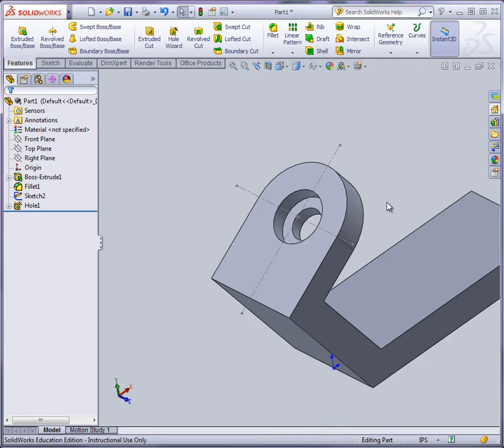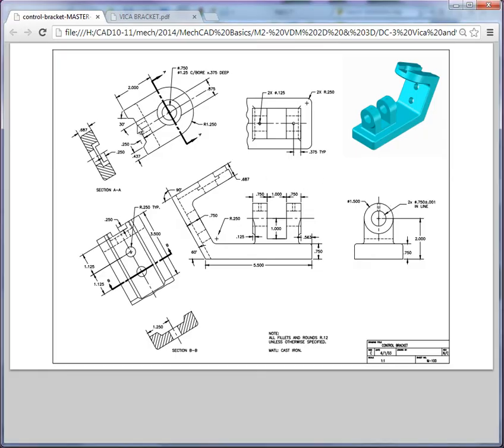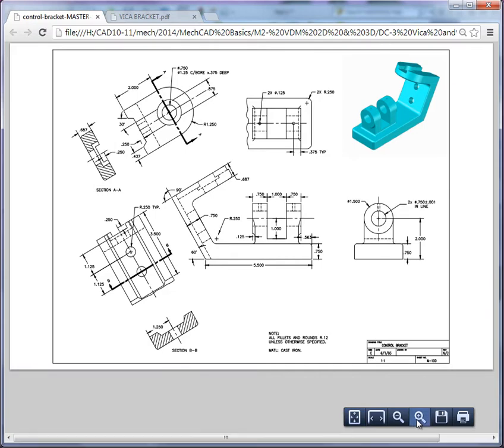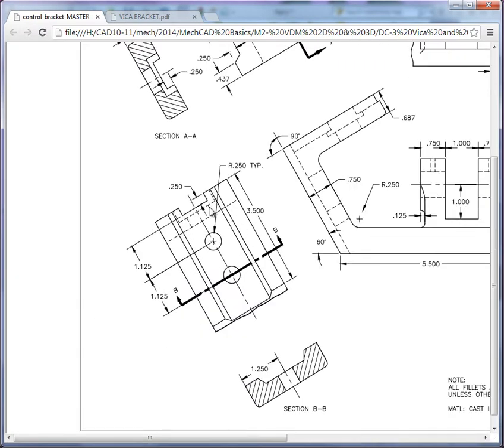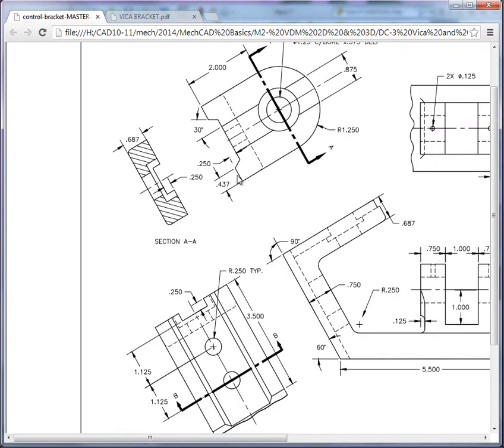As we proceed now, let's take a look at the slot. This center slot that goes through, you can see that we're actually going to be working on the opposite side, right? Or auxiliary face B here. And if we take a closer look here, we can see what the dimensions are. Right? We got about 250 depth. And if we look here, we got 0.875 total length of the opening there. Okay? And you can see how it's centered on that face.